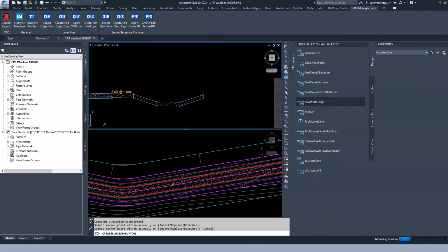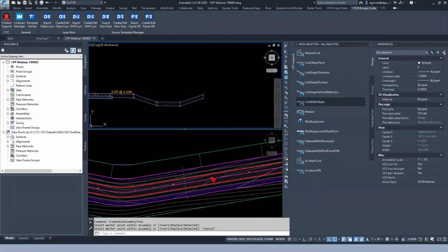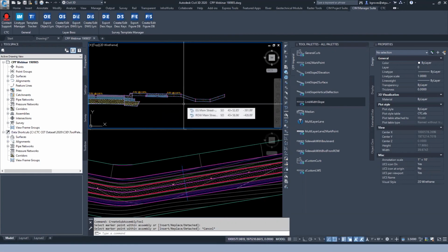And then you can have that. You can play with this. You can make these as wide or as shallow as you want. If you have an alignment or profile or feature line that you want any one of these outside point codes to track with for your drawing in a little bit, you can definitely use targeting to achieve that. But at the beginning of the presentation, I mentioned that these are Lego blocks, if you want to think about it that way, or they're the tiny little Lincoln logs that allow us to start putting together our design.